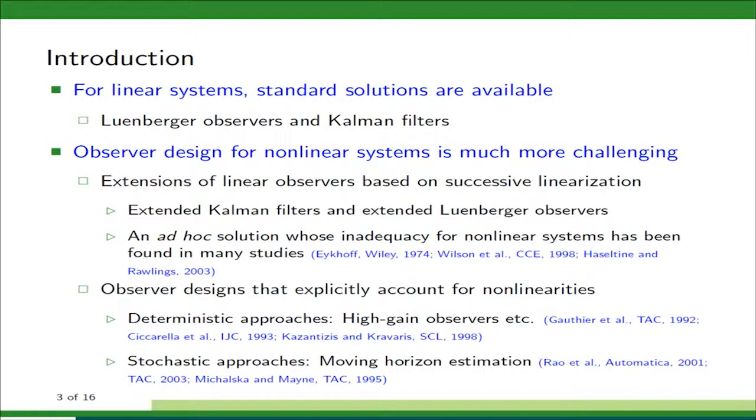For linear systems, there are standard solutions to state estimation. There are Luenberger observers and Kalman filters. However, state estimation for nonlinear systems is much more challenging. One approach is to linearize the nonlinear system successively at each sampling time, and then apply the linear solutions to the linearized model. For example, extended Kalman filters and extended Luenberger observers. Actually, these designs are widely used in the industry, especially extended Kalman filters.